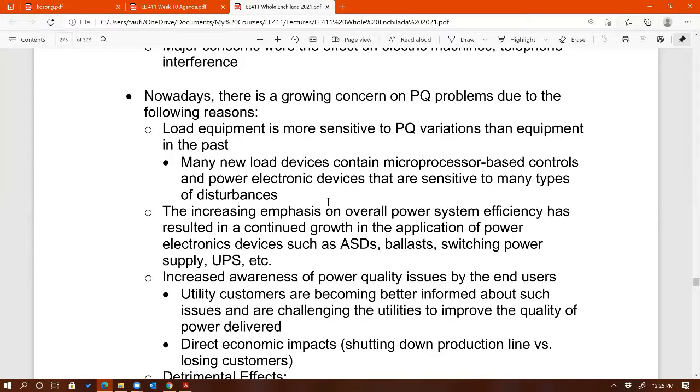I turned on the PLC first, right? And the PLC is working just fine. And then as soon as I turned on the adjustable speed drive, and they're connected to the same secondary side of the transformer, sure enough, the PLC shuts off. It's really interesting to see that as soon as I turn on the adjustable speed drive, the PLC shuts off.